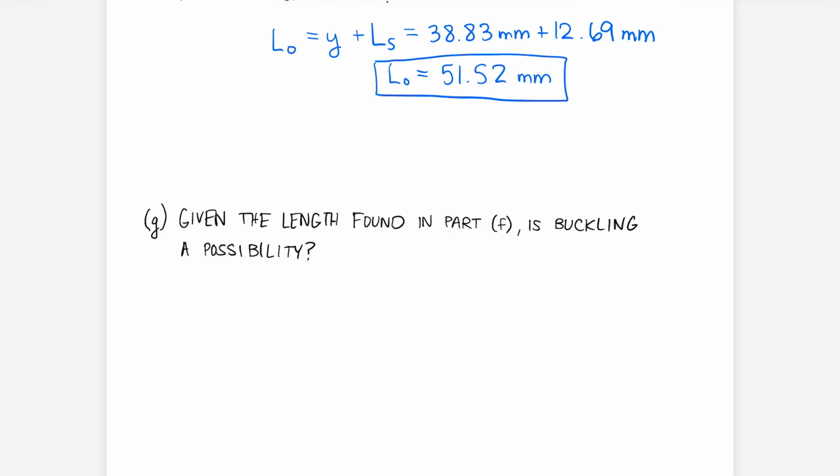Well, we found an equation for the free length to have absolute stability. We said that it must be less than pi times d divided by alpha, times the quantity 2 times E minus G, divided by 2 times G plus E, to the 1/2 power.